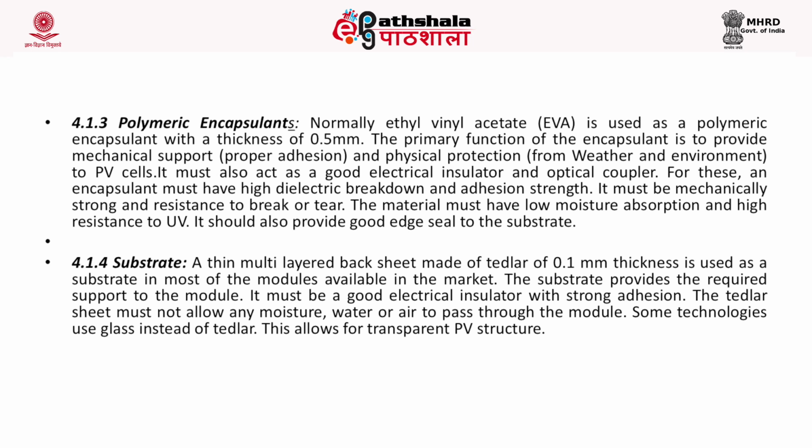Now, what is the substrate? A thin multi-layered backsheet made of Tedlar of 0.1 millimeter thickness is used as a substrate in most of the modules that are available in the market. The substrate provides the required support to the module. It must be a good electrical insulator with strong adhesion.